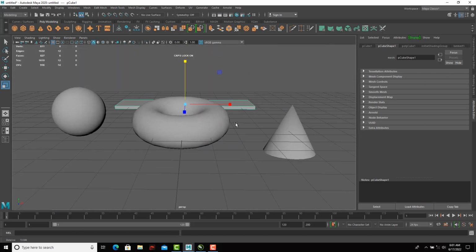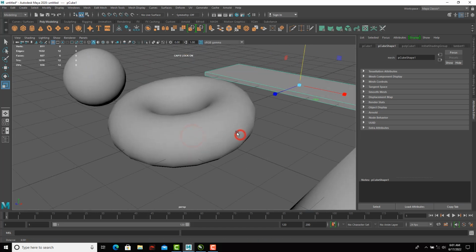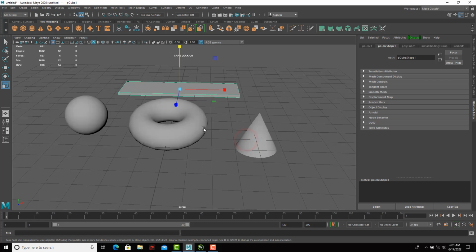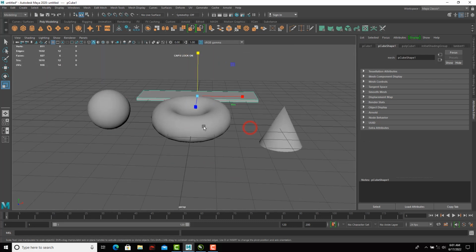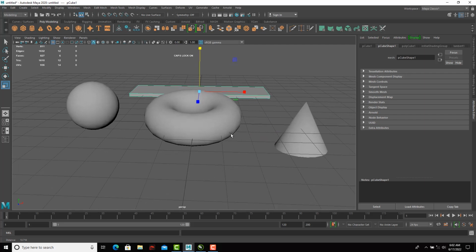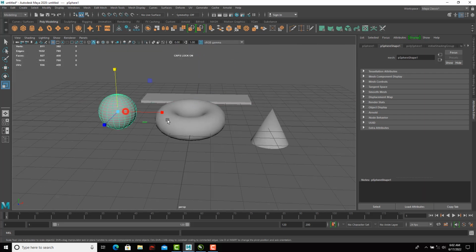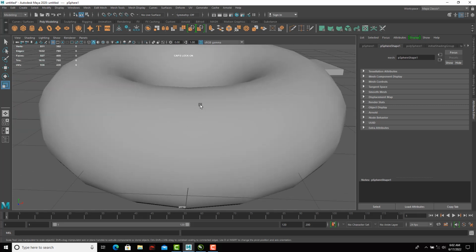Very, very important. So you need to learn how to blend or switch between each of these. You can see what I'm doing. So if I want to zoom now, zoom this guy close, like something like this, I have to hold down the Alt key, right click and zoom. You can see that this guy, if I zoom this, that sphere there is out of the camera.